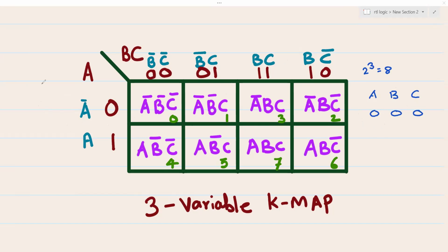So that's why for the first cell, when you say a decimal 0, it is showing you the first combination of three inputs A, B, C, that is 0, 0, 0. When you talk about the second cell, that is decimal 1, so here you see 0, 0, 1. So here you can write in the truth table form 0, 0, 1.